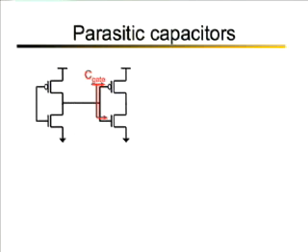So far, I have talked about what the gate input capacitance would be, and in the next slide I am looking at an inverter driving an inverter, which is one of the fundamental logic gates that we are looking at. The gate input capacitance would consist of the PMOS capacitance as well as the NMOS capacitance, which are nonlinear and obtained by doing the MOS-C simulation of these transistors. But apart from that, we all know that a circuit and system level evaluation should always incorporate all the necessary parasitics that come with the design.